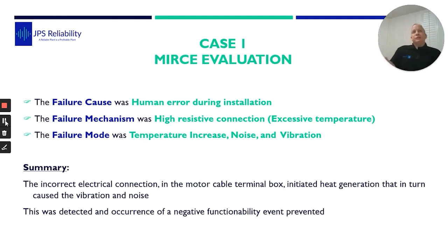So with this knowledge of condition monitoring, we've highlighted why the issue occurred, so we can look at ensuring that people follow procedures, and also, on the side of this motor, probably a double check on connections. But it enabled this company to put a quick plan in place to mitigate a stop in production, to manage that shutdown and change the motor out, because they knew they had to change the terminal box and just change the motor.